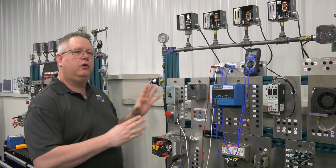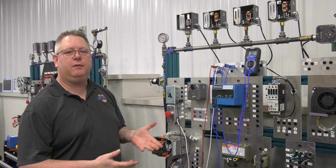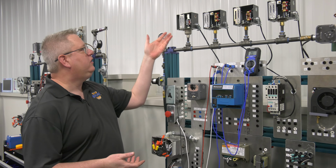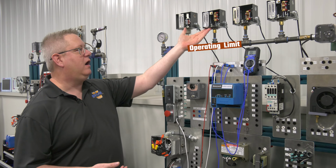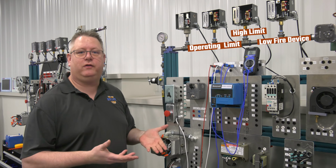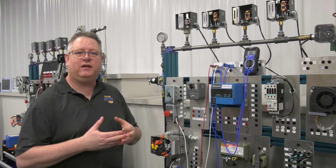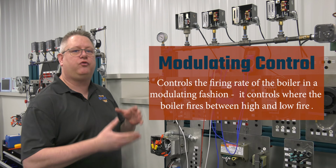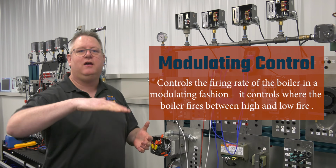We're going to take a close look at the firing rate or modulating control for a steam boiler. One thing that's unique about this device is that you may look at it and presume that it's a switch because our operating limit, our high limit, our low fire device are all switches, but in fact our modulating control has a different job. It doesn't actually turn the boiler on or off as much as it controls the firing rate of the boiler in a modulating fashion.